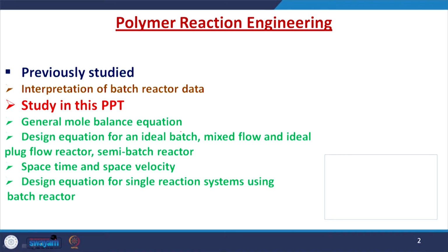And all these things are in situ with the various kinds of polymerization schemes, maybe solution polymerization, maybe emulsion polymerization, etc. Now, in this particular lecture, we are going to study the concept of the general mole balance equation. All these equations are of course mathematical equations. We will discuss the design equation for any ideal batch reactor, mixed flow reactor, ideal PFR, semi-batch reactor, etc.